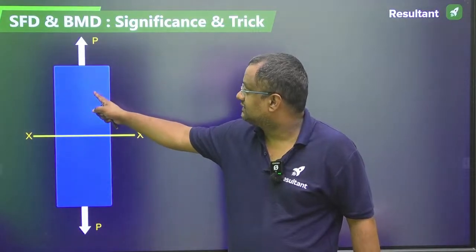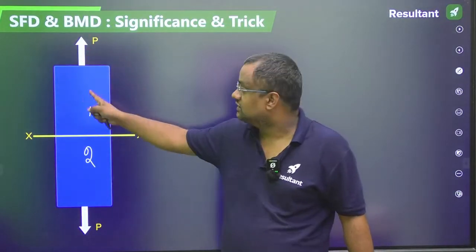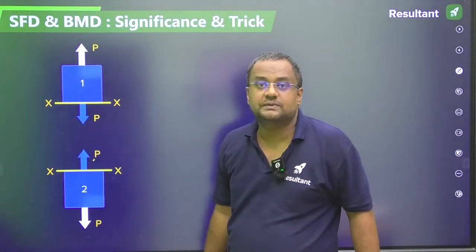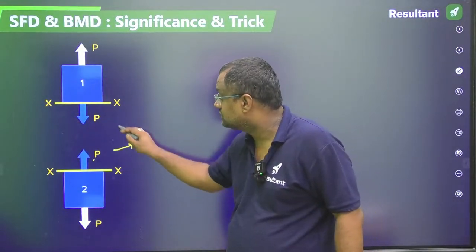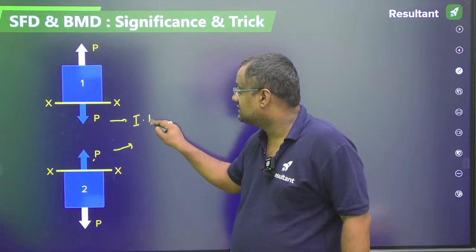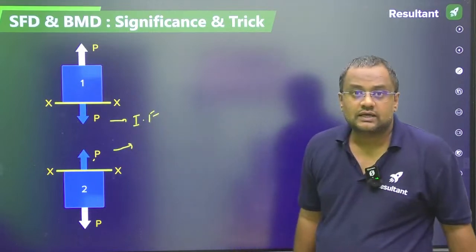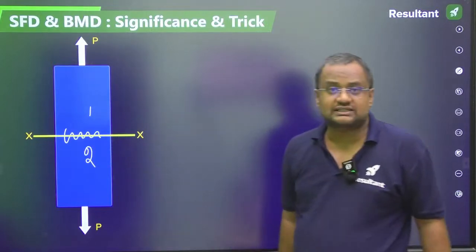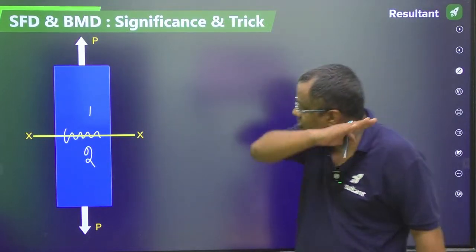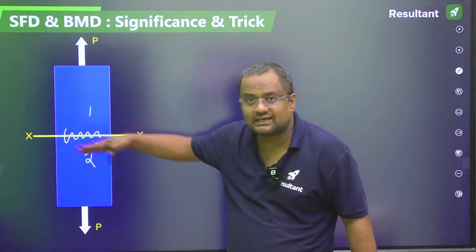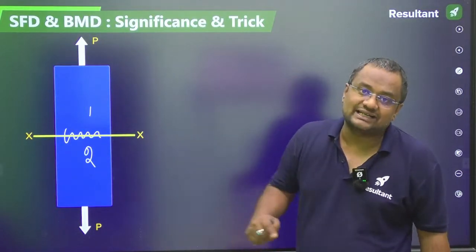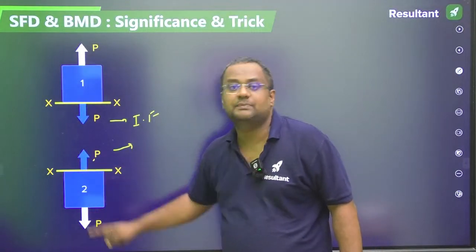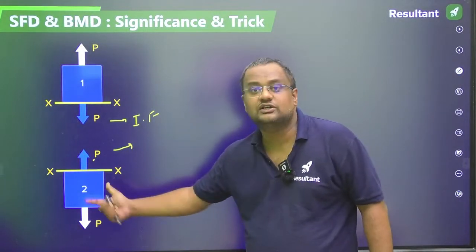Similarly, in one part, only this external force P is acting for balancing. Therefore, for balancing, in one part a downward force P is acting. This is an internal force, the one in blue color. Actually, here there is no force acting externally. Once we cut the section, then for balancing this part, a P comes for balancing this. Now it is in equilibrium.